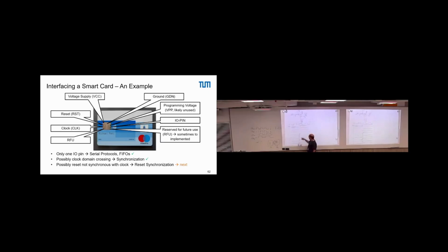They only see, register 3 sees this reset, which is delayed. Register 2 sees this reset, which is delayed. And this reset is still 0. So why should they act? Okay? So, meaning these two do not switch, then the reset is released here. And with the next rising edge, of course, the flip-flop does what it does. It just flips. But now we have the problem, we operate here with this rising edge on a partially initialized,